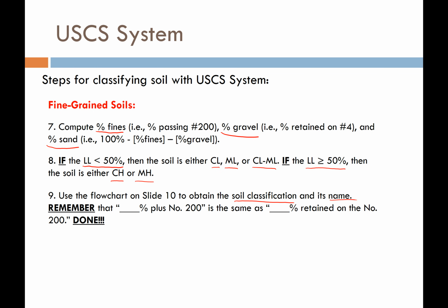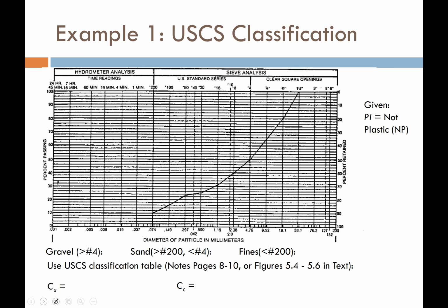A couple of things that are tricky, though, is that on this chart it uses this terminology of some percent plus number 200, and that throws a lot of students off. Really what is being said on this chart is the percent retained on the number 200. So plus 200 is the same as retained on, just to keep it consistent with the terminology that we've already been using in this class.